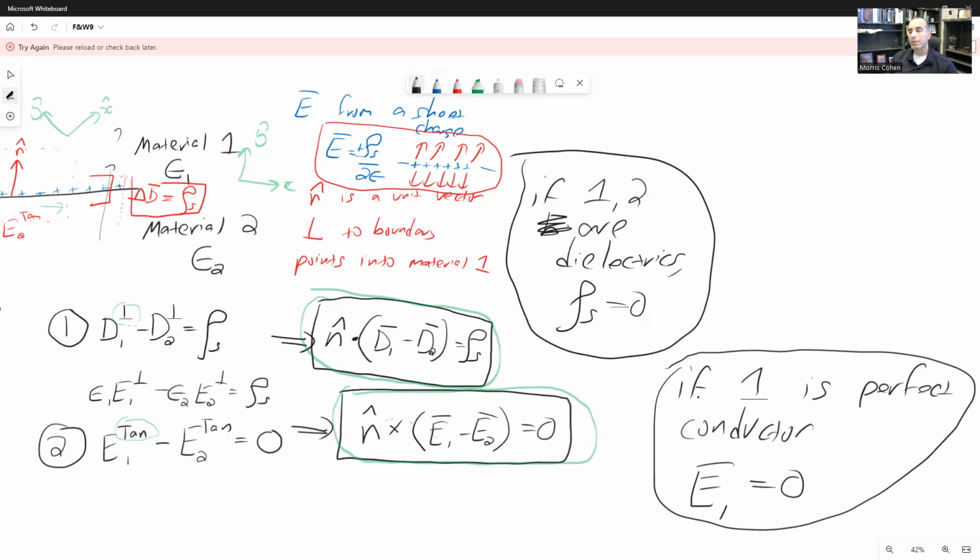And we're also going to encounter this as critically important when radio waves strike surfaces. So anytime a radio wave bounces off of an airplane, for example, in a radar system, we're not going to be able to understand how the radio wave interacts with that metal surface on the airplane until we understand how fields interact with boundaries. And that's what these boundary conditions are going to give us. So this is a building block toward understanding reflections of radio waves off of objects that we're going to see later. And in fact, in a later lecture, we're going to talk specifically about the same equations for magnetic fields.